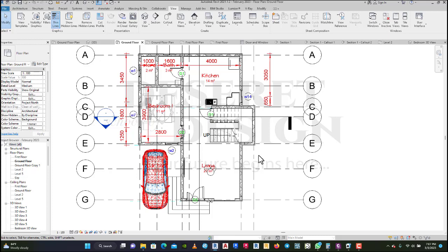There's a type of line. Maybe you don't want it solid, you want it maybe hidden line, or you want it dot. How do you do that? To do that, you have to go to the items, their actual distance, and change their default setting. So which thing will I use? Let me use one of the elevations to illustrate.